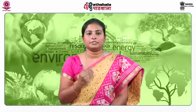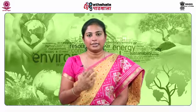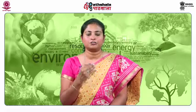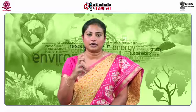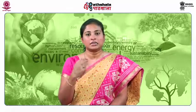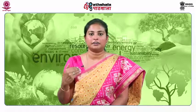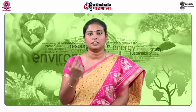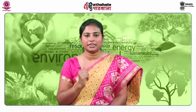Now, the next component is the daily and final cover at the top of the landfill. The cover protects against the entry of water into the waste during precipitation. The cover layer is composed of synthetic and natural materials. For daily cover, about 150 mm of soil is placed on each layer of waste. In addition to preventing leachate from escaping through the sides of the landfill, it also protects against disease vectors, fire, odor, blowing litter, scavenging and contamination of the environment.